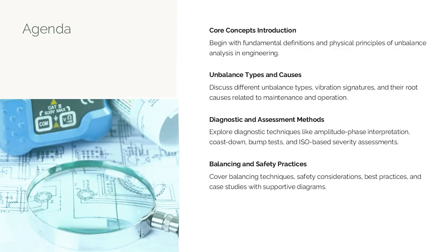This presentation follows a structured flow covering all essential engineering aspects of unbalance analysis. It begins with core definitions and physical principles, followed by a segmentation of unbalance types and their vibration signatures. Next, it addresses the root causes of unbalance and how these relate to maintenance practices and operational environments. The agenda continues with the severity assessment methodologies based on international ISO standards, providing the engineer with a robust framework